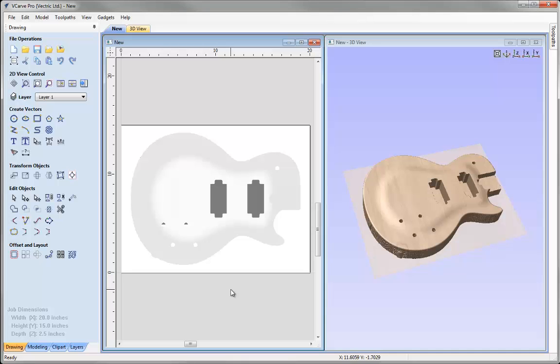The part's effectively ready at this stage for me to cut it, but what I don't want to do is machine down the vertical edges of the part using a 3D toolpath. I want to limit the area that the 3D toolpath is going to cut and then use a more appropriate 2D toolpath in order to machine the pockets and to profile around the shape of our entire part.